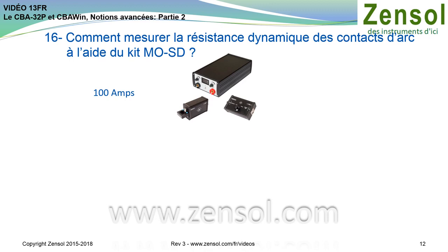For circuit breakers, this test is carried out at rated speed or at slow speed during an opening operation. The main advantage of this test is that it allows us to determine contact wear and arc contact length, contact misalignment or mismatch, as well as other anomalies by simple resistance analysis.